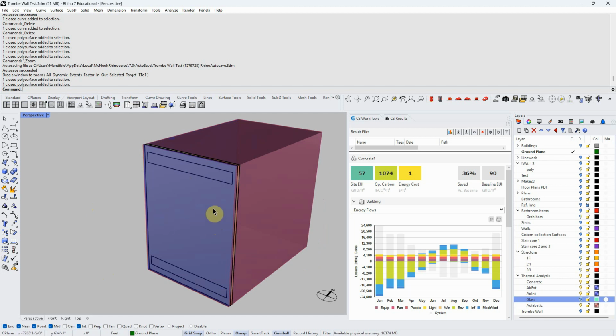and that allows us then to take a lot more advantage of the heat in here because as soon as the sun goes down, this is going to cool down and we're going to start losing heat out of here, even if we have a pretty good piece of glass in front of it. So we want to dump as much heat as we can during the day into the space.